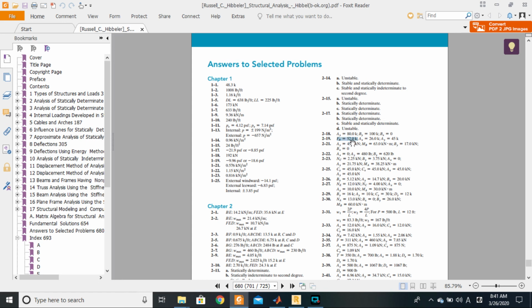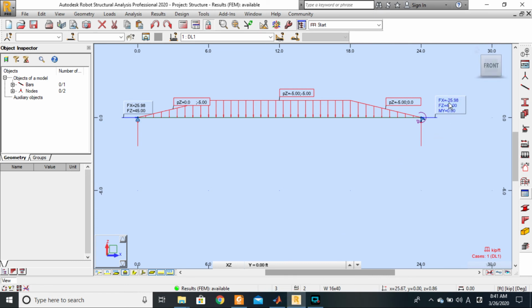But if we want to know if we are correct, then we need to calculate what the components of this FB are and see whether it corresponds to what we are having here. So if it is inclined at 30 degrees here, then the component that closes the angle, which is cos, is the vertical component, right? And so FZ here is supposed to be 52 cos 30 degrees.